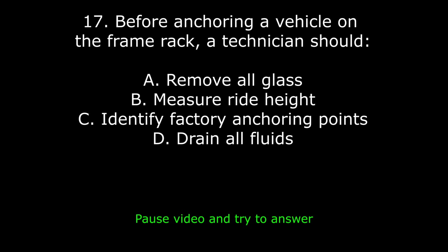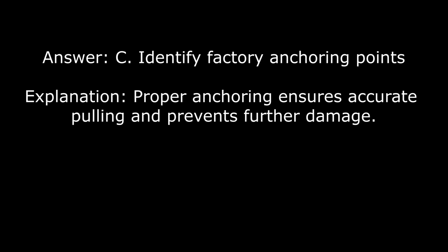17. Before anchoring a vehicle on the frame rack, a technician should A. Remove all glass. B. Measure ride height. C. Identify factory anchoring points. Or D. Drain all fluids. Answer: C. Identify factory anchoring points. Explanation: proper anchoring ensures accurate pulling and prevents further damage.